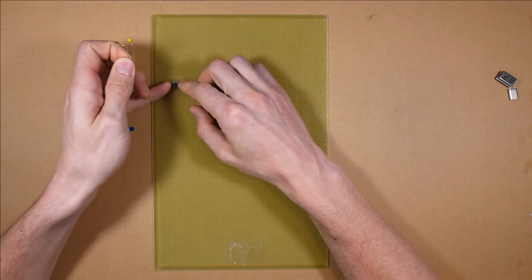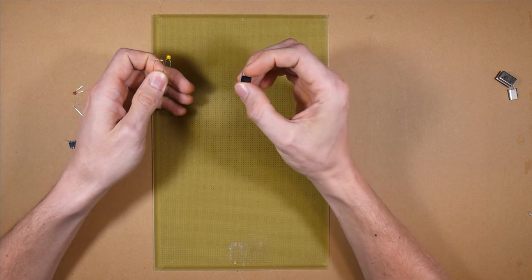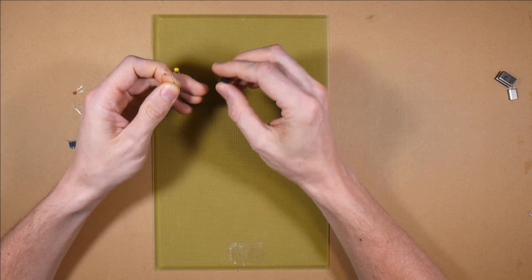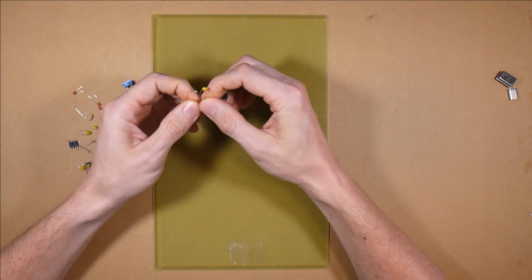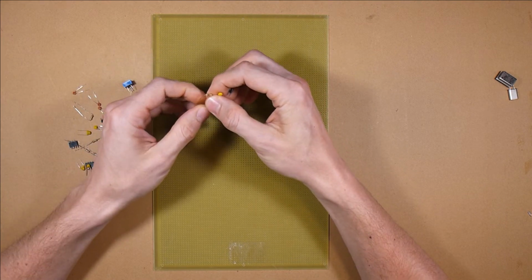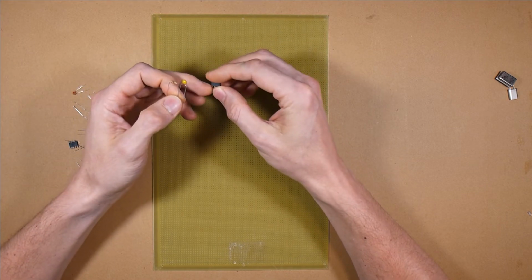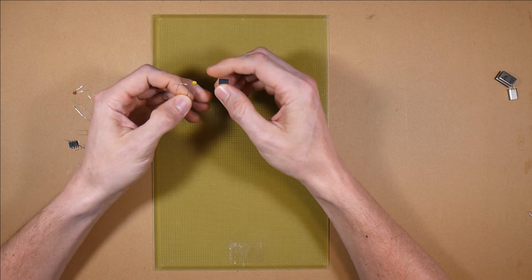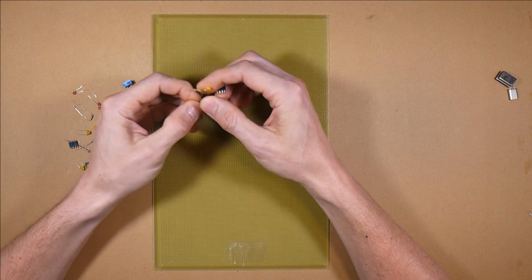And luckily for us, the LM555 timer IC will do this for us. Just with an external capacitor and resistor, it will control the charge and discharge of these components, and we'll be able to create a clock pulse from it, adjustable clock pulse.